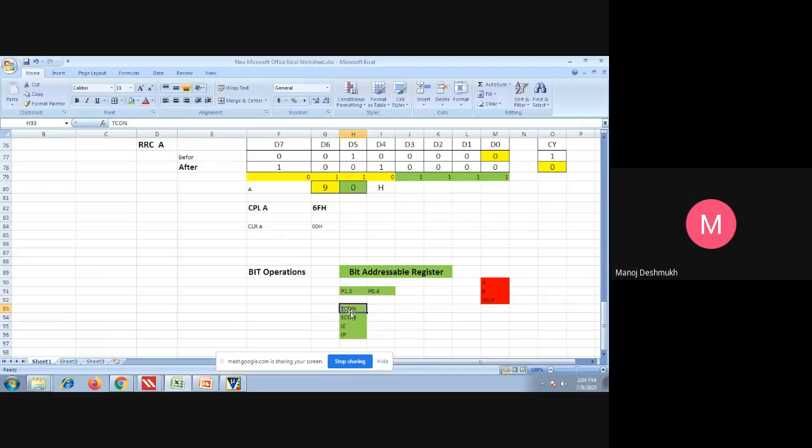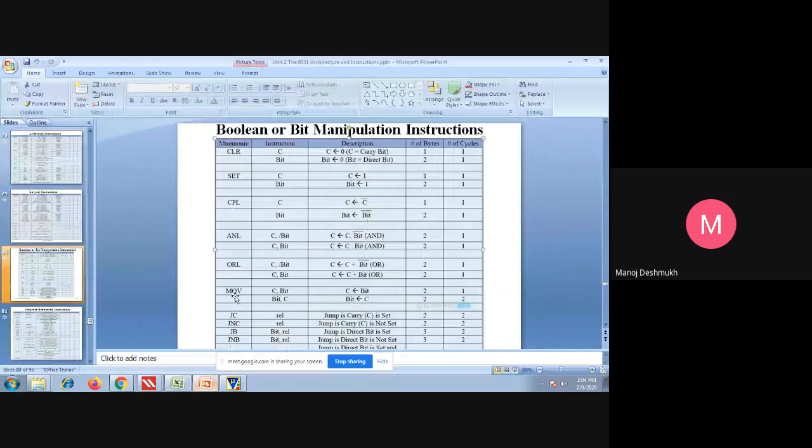So from those, we are able to access any one bit, like suppose PCON bit 0, 1 or 2, whatever, SCON bit 0, 1, like that. In this case, we are able to access a particular bit without affecting the other bits. So we consider these types of registers as bit addressable registers, and bit manipulating operations are performed on these registers only. Are you clear?